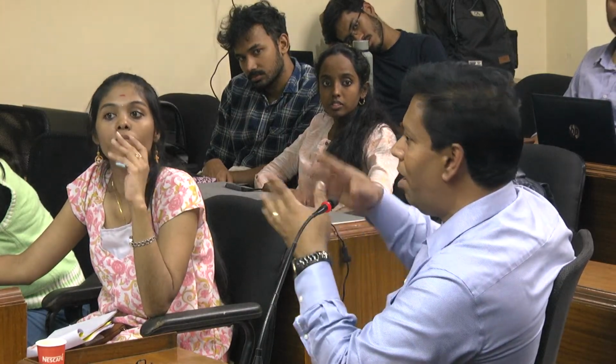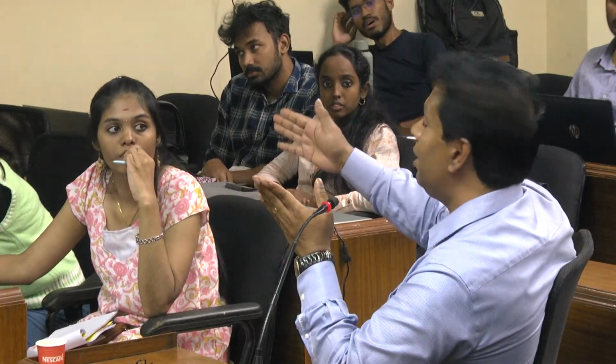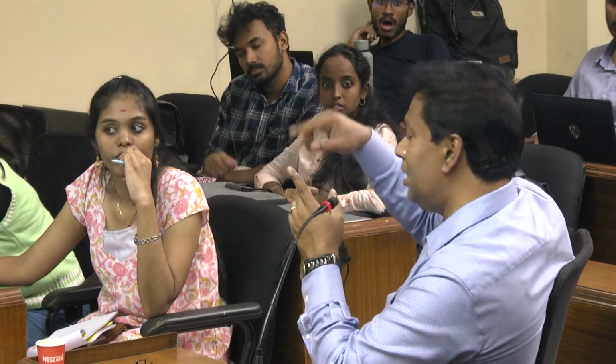One way is if your simulation somehow stops somewhere, you can start from there. The other one is if you want to analyze some data at a specific time, because it's a transient case, so you can use the data at that time. And also if you want to make an animation, you can use the whole data set. Yeah, there are three reasons.